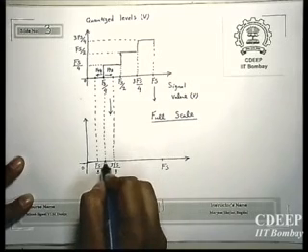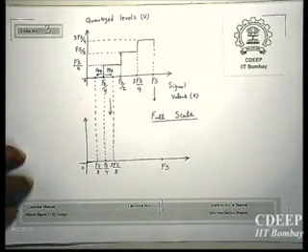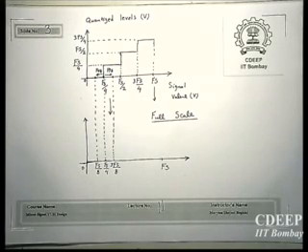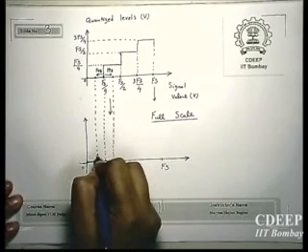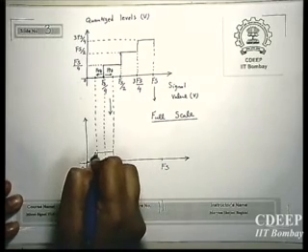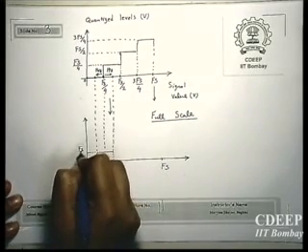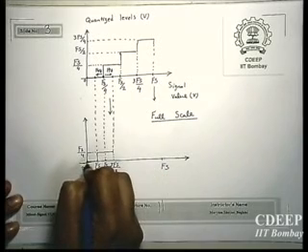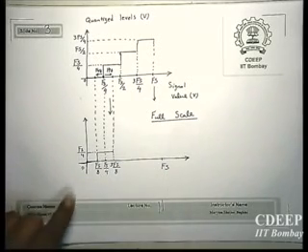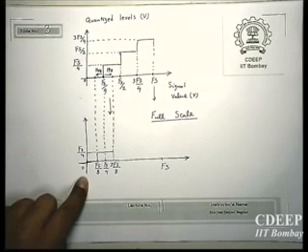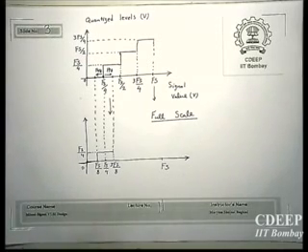We say that if my signal is Fs by 4 plus or minus some delta around Fs by 4, I map it on Fs by 4. And of course here I should say that if my signal is around 0 plus or minus Fs by 8, full scale by 8, I have considered I don't have negative signals, therefore I don't go below 0.